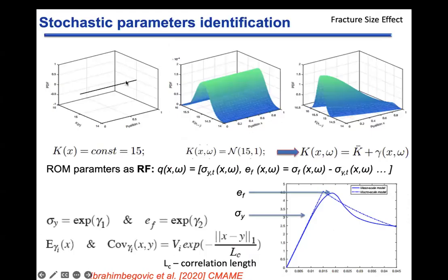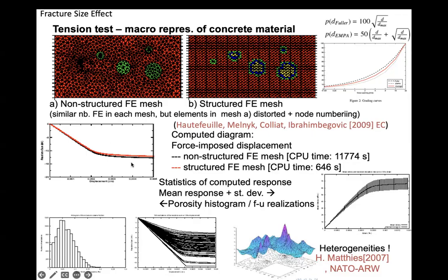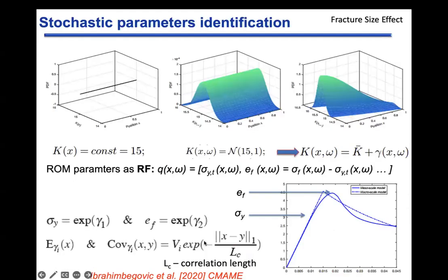And then basically, the results are different realizations given here, and you can homogenize. That means your properties are constant throughout this element, or they can be a random variable, or if you really want to have a size effect, they have to become a random field. We estimated this random field for yield stress and for the ultimate stress, or rather the difference between ultimate stress and yield stress, so that it is always positive, to make sure that ultimate stress is bigger than yield. This is represented by a so-called isotropic random field with a parameter that quantifies the correlation length.